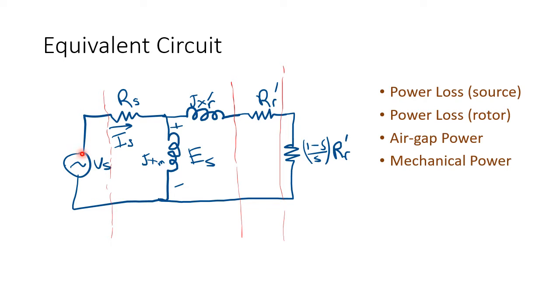Then it's going to go into the wire, and because the wire has some resistance, we're going to count it for this RS, and that'll be the resistance we're going to call it. And then what's going to happen is that resistance, so current moving through a coil should have produced electromagnetic waves. And how we're going to present that in the circuit is to show induction coil, and that will in essence create the voltage equivalent to having a gap separation between this side and the actual so the stator side and the actual motor side, the rotor side, which is spinning.